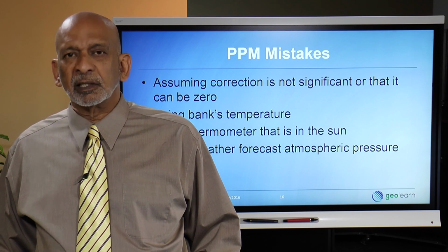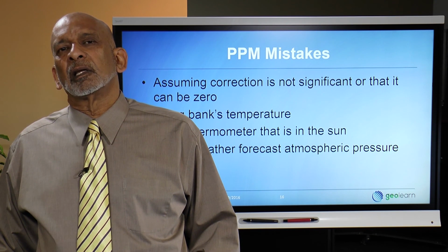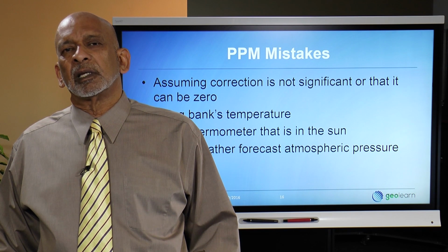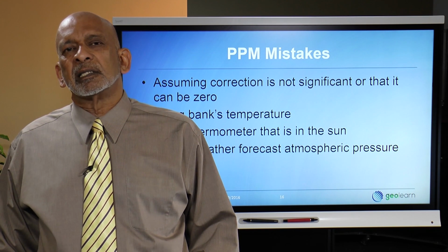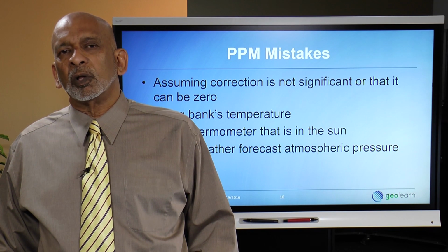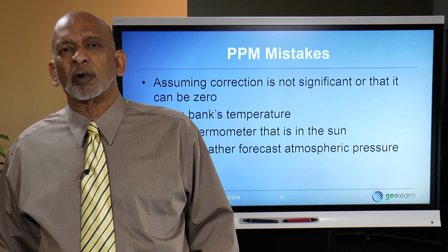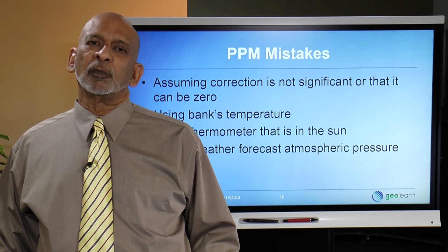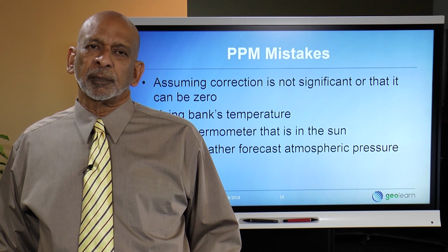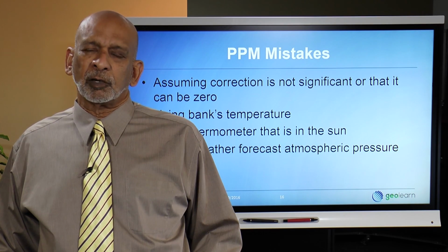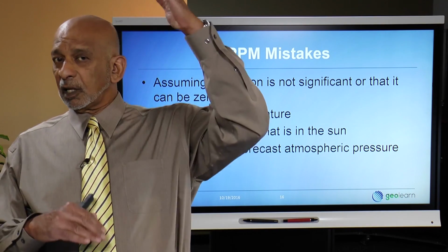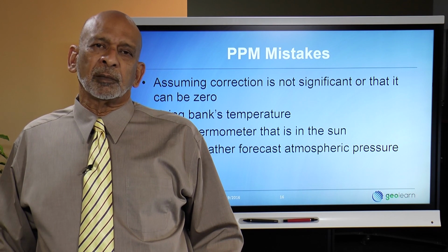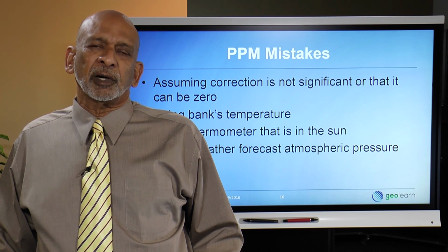The other is that weather forecasts correct all the way down to sea level. So when they report what the barometric pressure is, it's as if they dug a hole all the way down to sea level and placed the barometer there. Now, they don't actually do that. They know exactly how much the elevation of a particular point affects the barometric pressure, or in other words, the weight of the column of air above the barometer, and they make that correction.